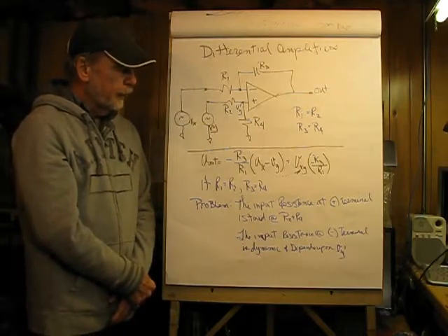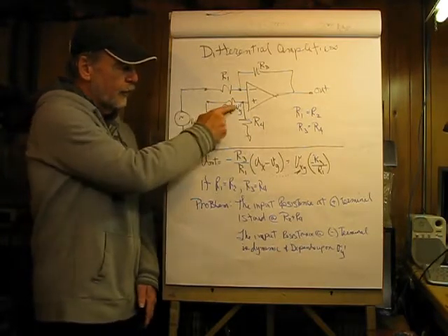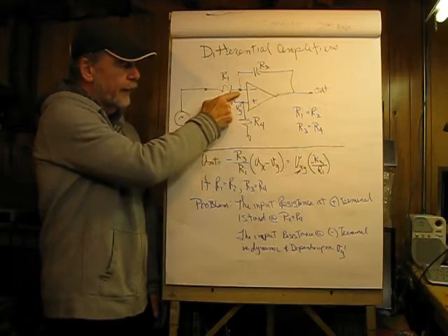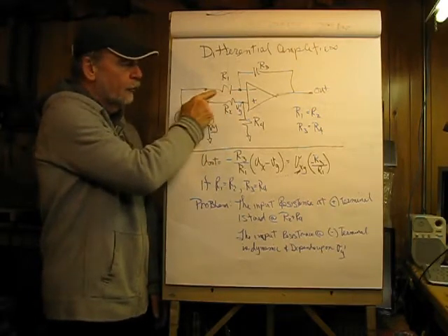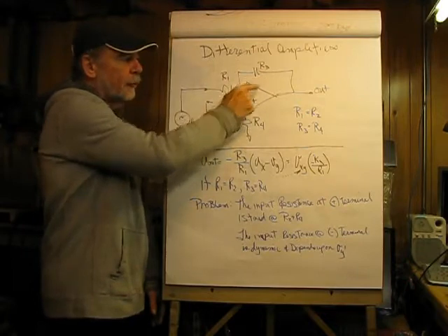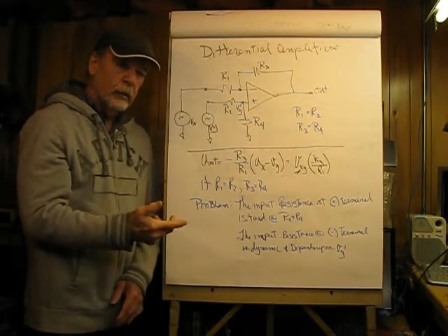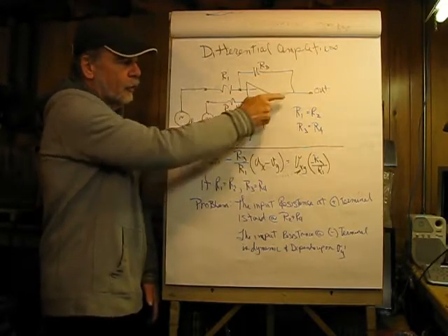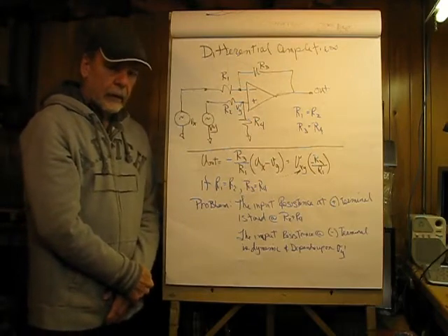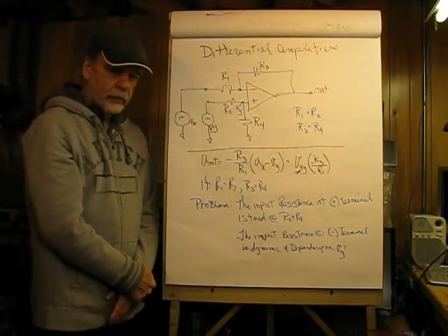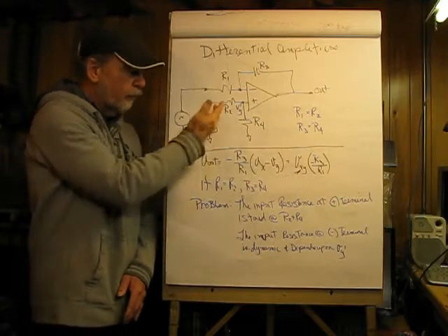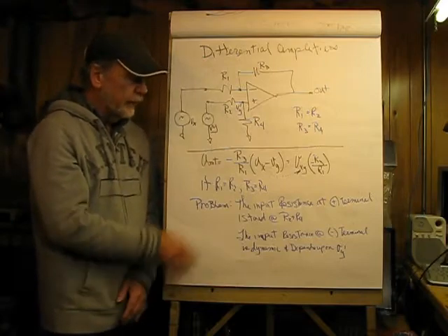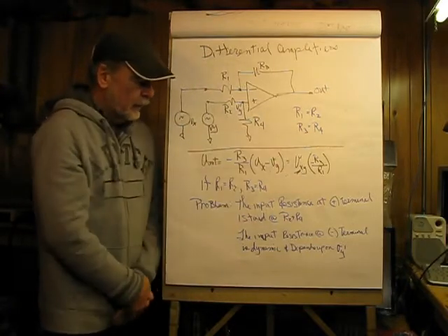So the way we found the gain of this before is we found the voltage at Y prime using voltage divider, and then transferred that up to here and found the currents flowing through this resistor, pushed them through R3, and in the case of DC we were very careful to note polarities, and then added this voltage drop to this voltage to find V out. Now, as it turns out, that's a very good exercise in pushing currents, finding out in that method what the gain would be.